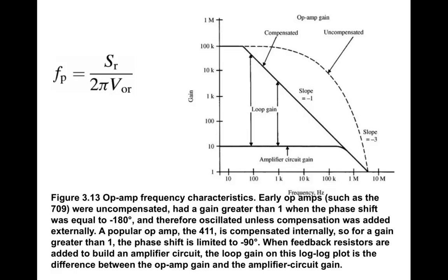That's kind of a classic thing in electrical engineering, meaning if you want to amplify a lot, the op amp itself, once you get above a certain frequency, is going to begin to cut off some of your signal output. If you don't want to amplify very much, then you can get much higher frequencies out of your amplifier, but once again, you can't really amplify very much. So that would be sort of the last thing really in op amps that we want to look at in this lecture.